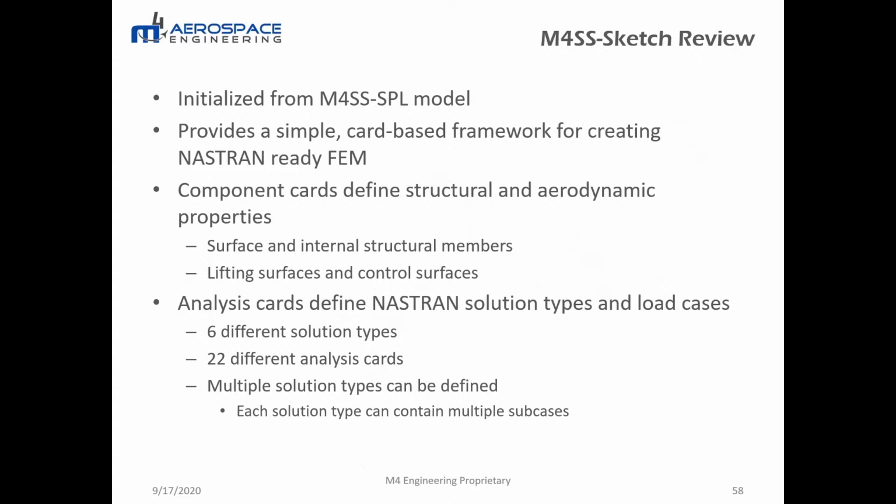And then these sketch models can contain both the component and analysis cards, where the component cards define structural and aerodynamic elements, and then the analysis cards are used to define Nastran solution types and various parameters within that load case. So there are 6 different types of solutions available, and then 22 different analysis cards can be added to them. And then multiple analyses can be added to any model.